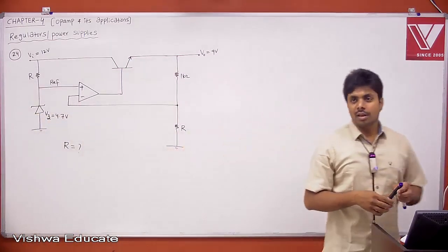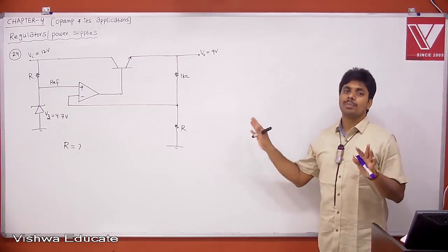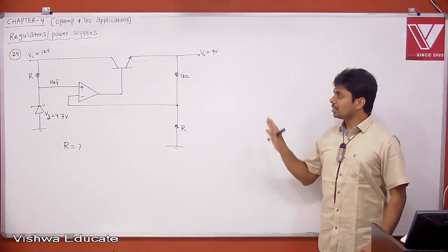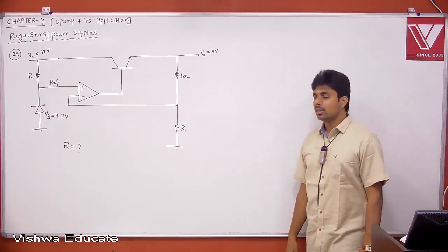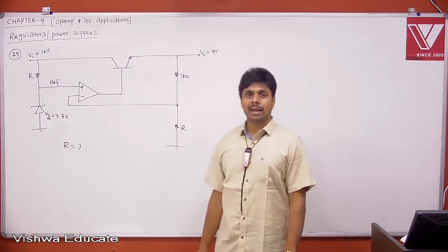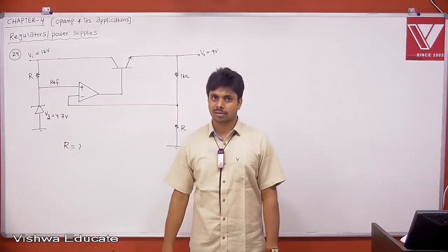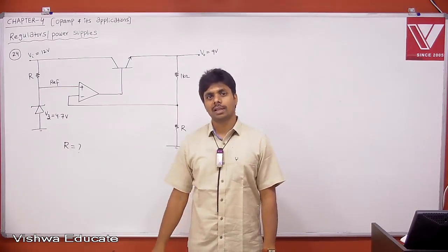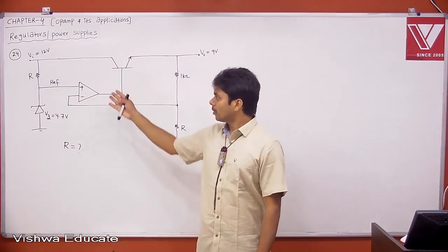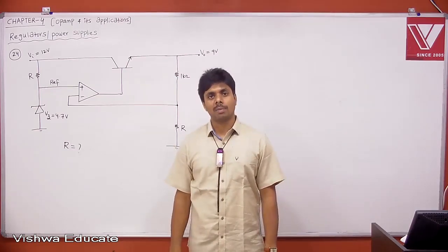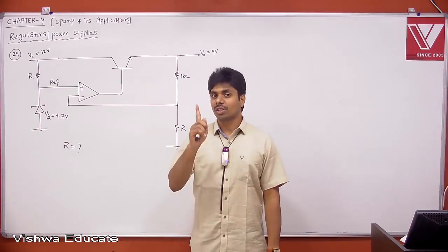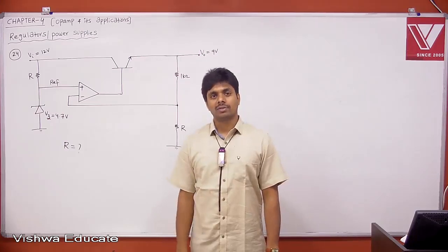How will you solve? Remember, this is nothing but an op-amp problem. If you treat this as an op-amp problem, tell me, is the op-amp in negative feedback or positive feedback? Definitely it should be negative feedback. If the op-amp is in negative feedback, then the virtual ground concept is valid.